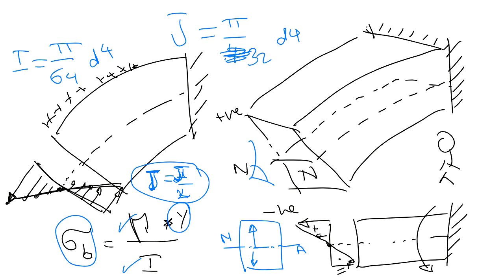Okay? So as you can see, guys, if you are trying to measure the distance between the farthest point on the top layer and the neutral axis, you will end up that this farthest point has the maximum tension stress. Why? Because the distance is the biggest distance, and not only this, the sign of the y is positive. You got it? So what about the lower layer?